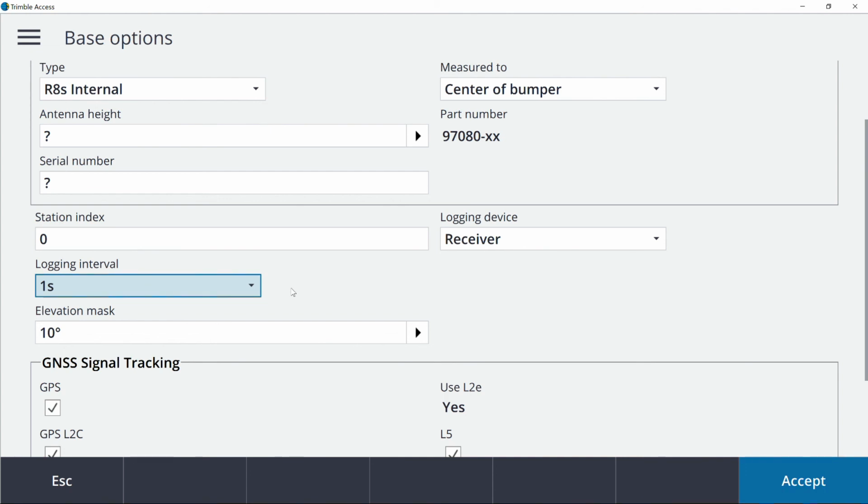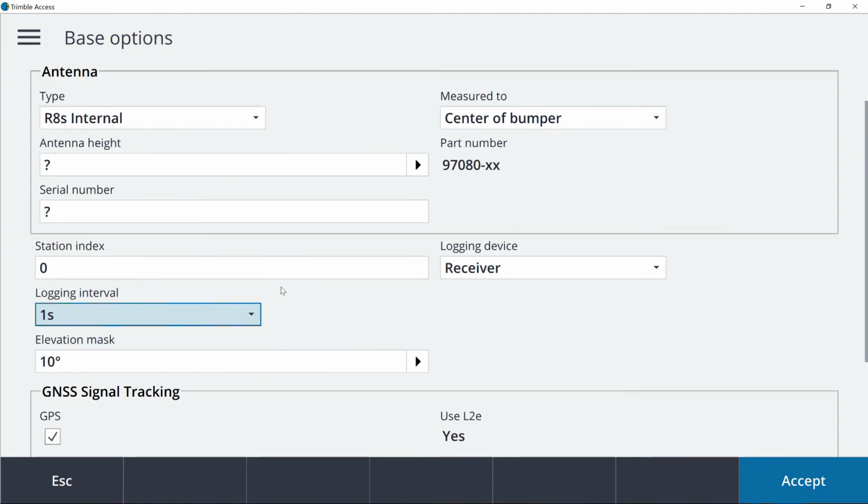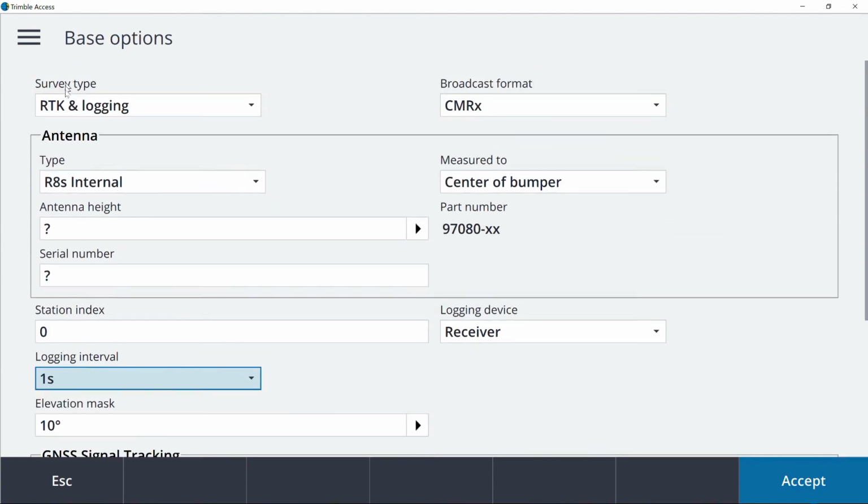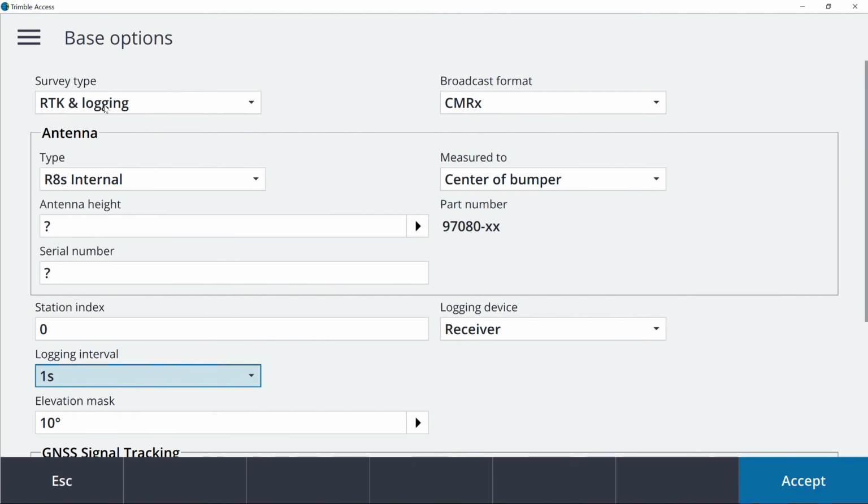So for me, I always like to record a little bit more, knowing, hey, if I don't use the extra, no big deal, but I'd rather at least be able to meet what's in common with what I'm post-processing against. I especially like leaving this at 1 second when doing larger control setups where I'm doing multiple sessions at the same time off multiple receivers. I always find having more data is better because if I need to crop out some noise, I have that ability after the fact.